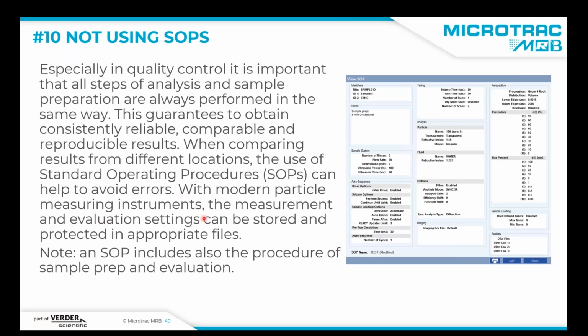Every modern particle analyzer, laser diffraction, image analyzer, all these settings that you use for sample feeding, everything that is instrument related is saved in the file. So just by calling up this SOP here, you make sure that your instrument settings are always the same. But there's more to a good SOP than just instrument settings.